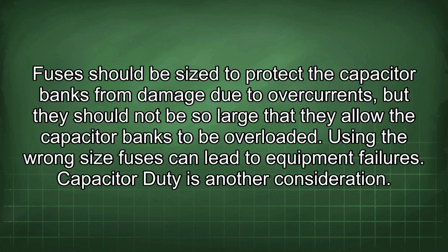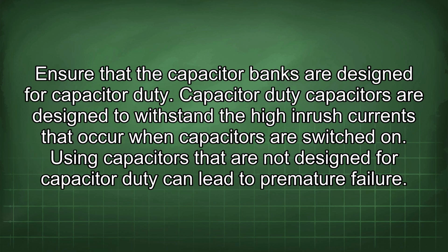Capacitor duty is another consideration. Ensure that the capacitor banks are designed for capacitor duty. Capacitor duty capacitors are designed to withstand the high inrush currents that occur when capacitors are switched on. Using capacitors that are not designed for capacitor duty can lead to premature failure.